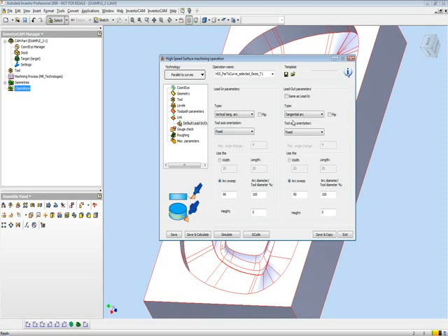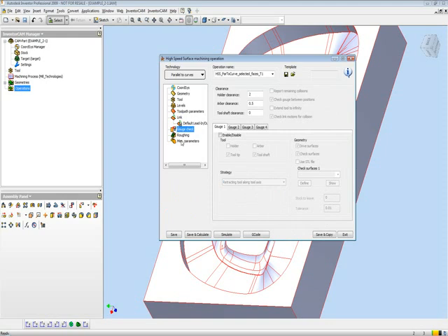However, my lead out, I'd like to have it at tangential. Now, when I have it as tangential, though, I don't want it to go exactly on the surface itself. Rather, I'd rather have it pick up from the surface as it's leaving the surface, not to leave a mark. So I'll set my height at 1mm. Now we'll go into our gouge check.